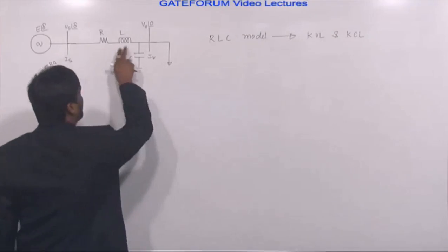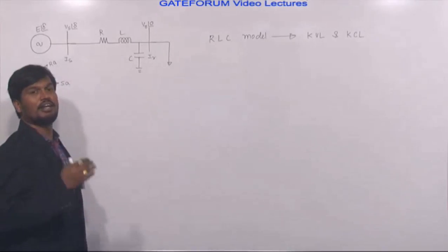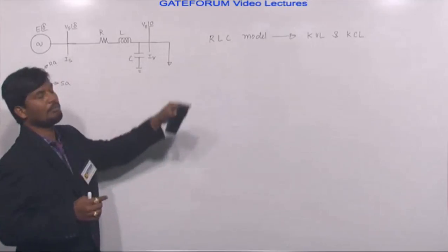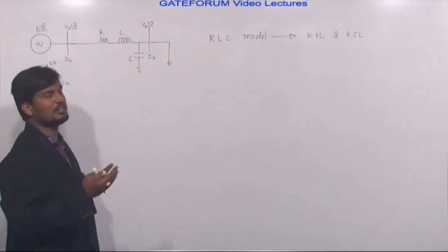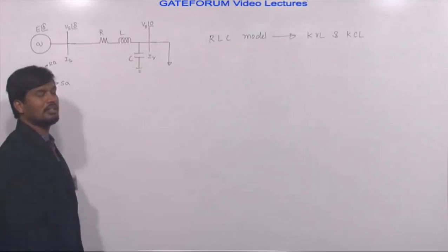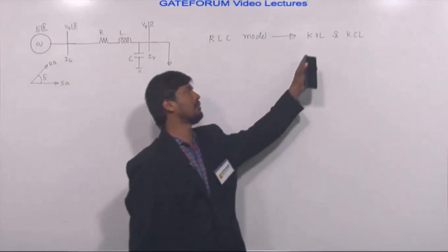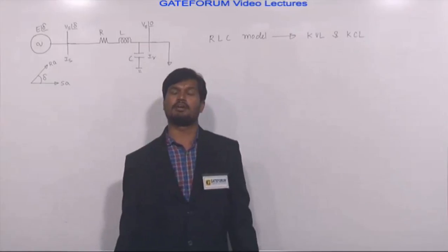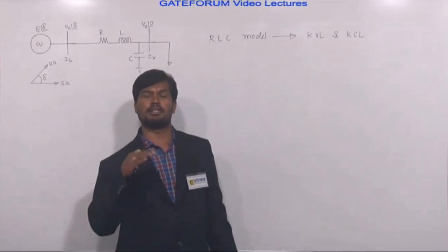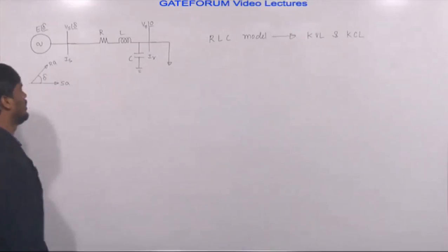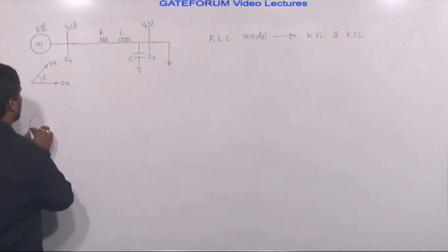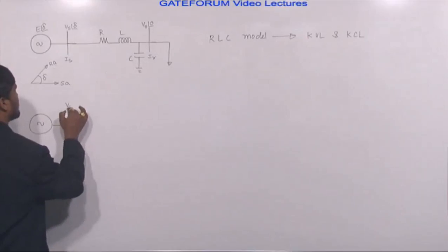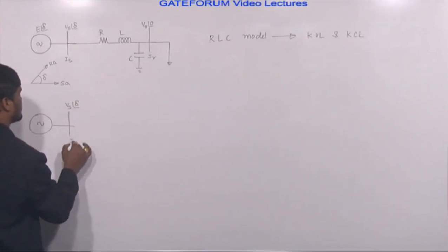In India, we do not have one line. In India, we have infinite lines. As we have infinite lines, definitely we have to apply infinite KVL and KCL equations. Therefore, the number of network equations increases if we analyze the transmission line using KVL and KCL. As the number of network equations increases, complexity also increases. In order to reduce complexity and solve transmission line performance, the transmission line is always represented by ABCD parameters.